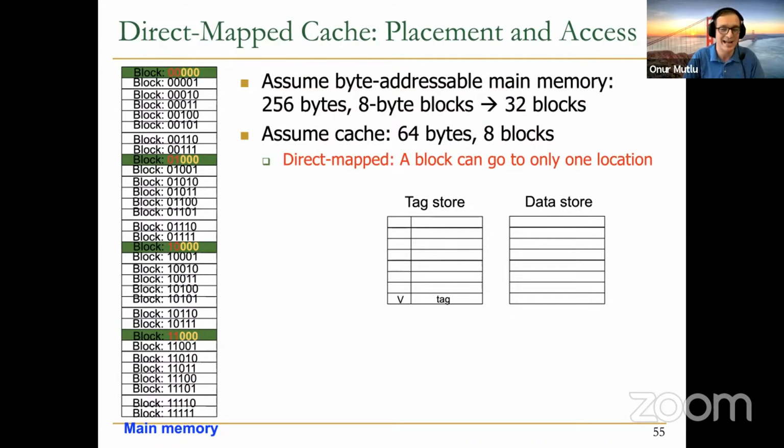So this is the valid and tag I showed you. This is our 8-bit address. The processor issues an 8-bit address. It's looking for this address. The least significant bits specify the byte in the block. They're 3 bits, since blocks are 8 bytes. The next least significant bits are a 3-bit index. Why 3 bits? Because you have 8 possible indexes into the cache. And then the tag is the remaining bits, 2 bits over here. So what do we do to query the cache?